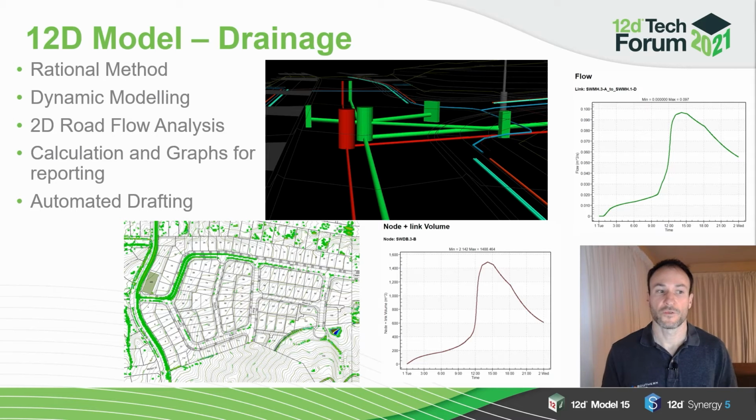It was great to have all these features in the one software that I could do all my drafting, do all of my updates, update a road, update a surface, and then rerun my dynamic calculations, see the invert levels change, tweak my orifice and weir elevations, check what heights I need for an outflow or an overflow. All these things was just being able to play and tweak with the model and not having to take it to another software. And it really sped up that design process in this stage of detailed design.